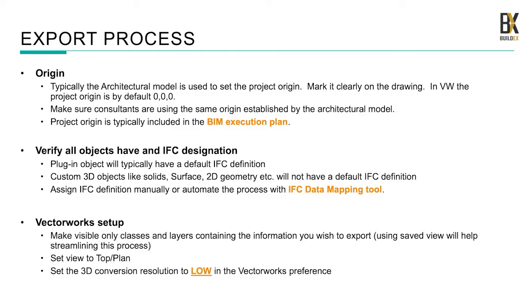So in summary, in the export process, there are a few very critical things that you need to remember. You need to all agree with your consultant where the origin of the project is, and it should be indicated in a BIM execution plan. Verify that all of the objects that you want to transfer to your consultants have an IFC designation. And in the file setup, you must make sure that the 3D resolution is at low, and that you set up your view to a top plan view prior to the export.